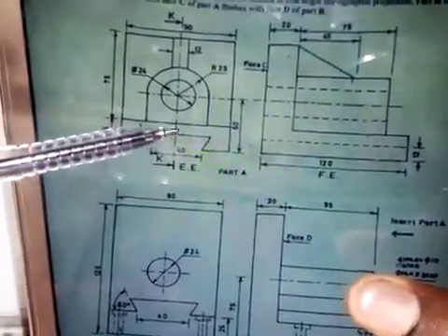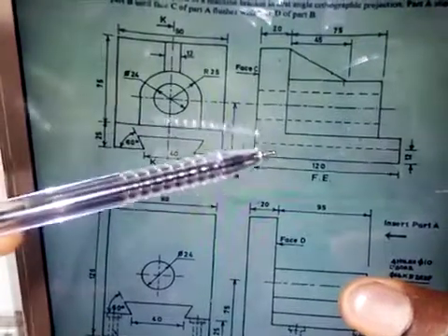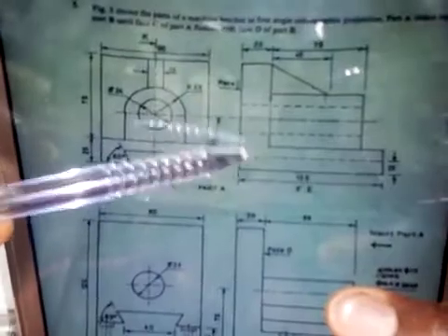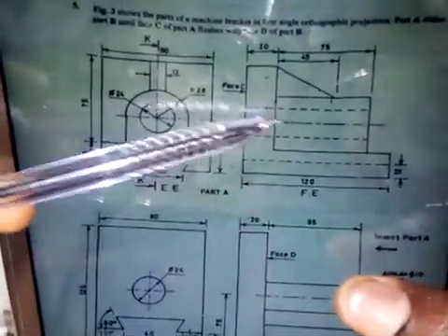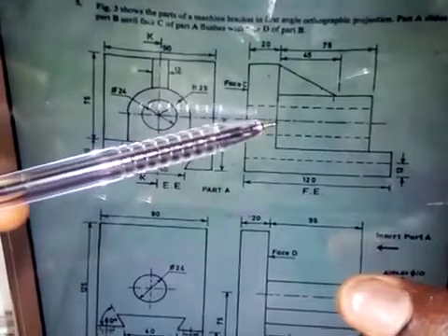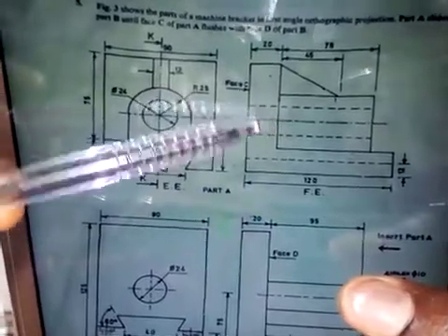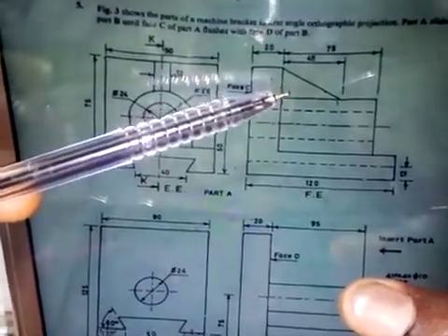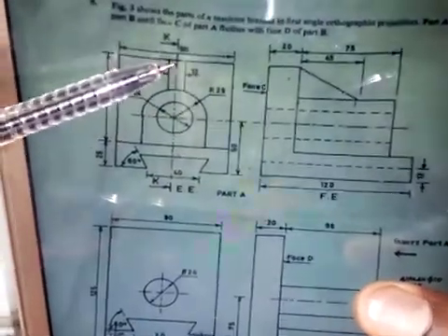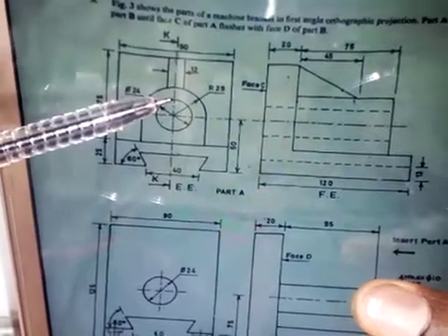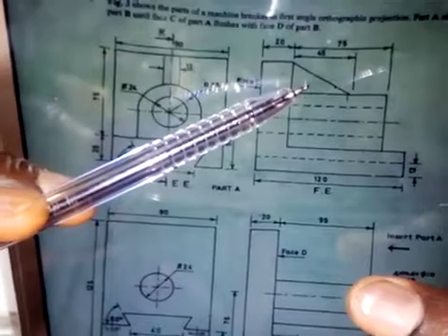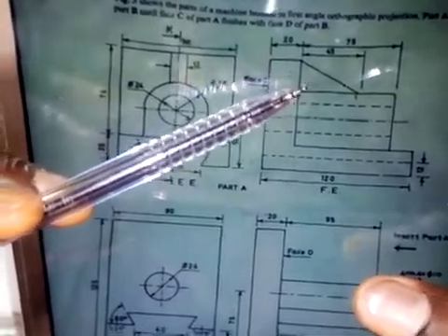But this part, as we have it, is a solid part. So we are going to arch this and arch this together with it, because they are both one component. Except the cylindrical part is not going to be arched, because we are not cutting it. Likewise, the web, because the cutting plane cut it down like this, will be left unarched. So take note of that.